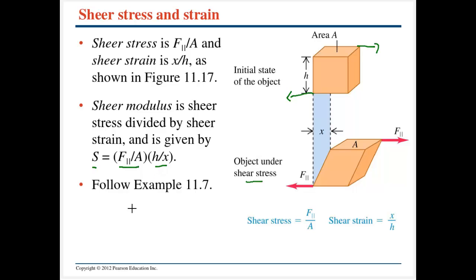And one thing to note, if you go back and look at table 11.1, all of the values for shear modulus are much smaller than for Young's modulus. It turns out that it's much easier to deform an object by applying these forces in a shear sense than trying to compress an object or pull it apart.